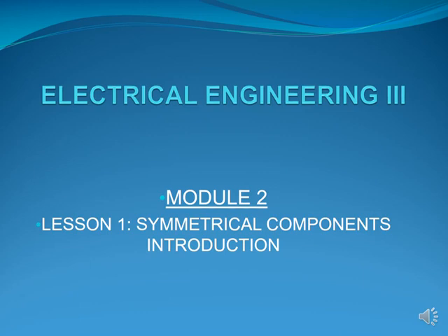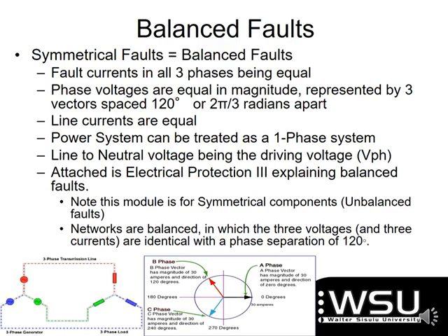This is our first lesson on our module 2, which is on symmetrical components. This part of the lesson is going to introduce the concept of symmetrical components. These are used when we are talking about faults in a system. We've already introduced our three-phase systems, mainly looking at your transmission lines. So when we have faults in those systems, this shows us how we break up the system so that we can work out what the currents and the voltages are within that system at the time that the fault occurs.